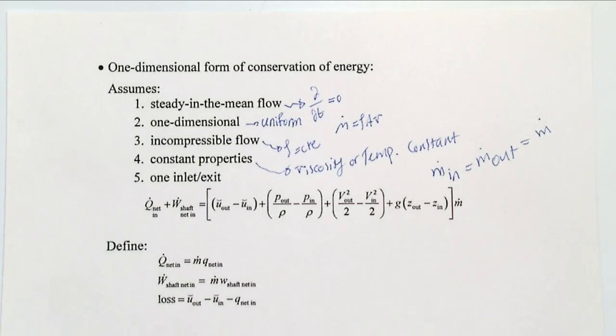Whatever V in could be different from V out, right? Because most of the time you have different energy, so it could be different. Also velocity changes, or maybe the area, like a nozzle, could be different. But what we know is that m dot, the total mass, is conserved, right? So m dot in has to be m dot out, because we have one inlet and one outlet. Then these two are the same, and we have one m dot.